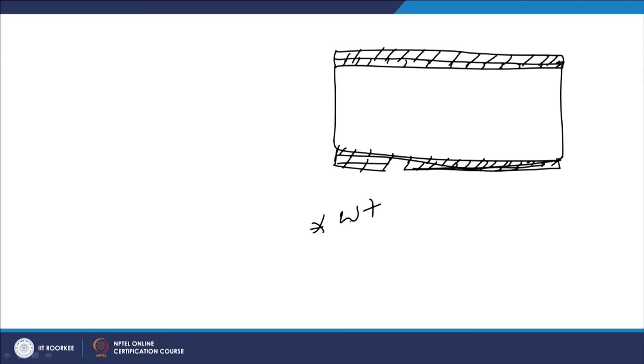The TBC coatings will be applied onto the substrate, which in turn increases the weight of the entire component as a whole. So, if weight is not a major issue, thick coatings can be applied for reducing heat transfer onto the main component, such as in thermal power plants.